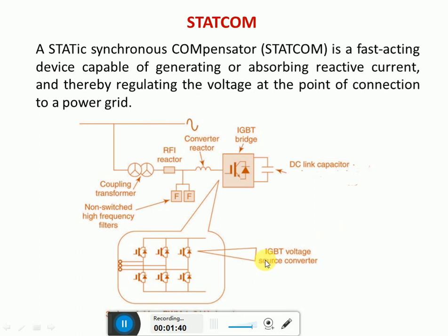Now this figure shows the basic structure of a STATCOM, where it consists of a voltage source converter, a DC link capacitor, a filter and a coupling transformer.